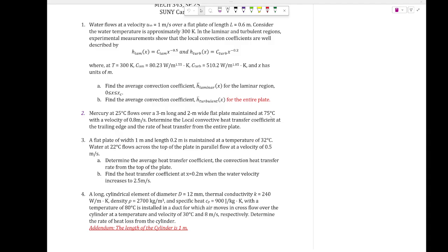Now there are like 5 parts of this experiment. The first one is called natural convection. What it means is that you have the heat gun, right? You're going to use it to raise the temperature to 60 degrees Celsius. Once the temperature gets raised to 60 degrees, you are going to wait till the temperature drops to 30 degrees Celsius. So 60 to 30.